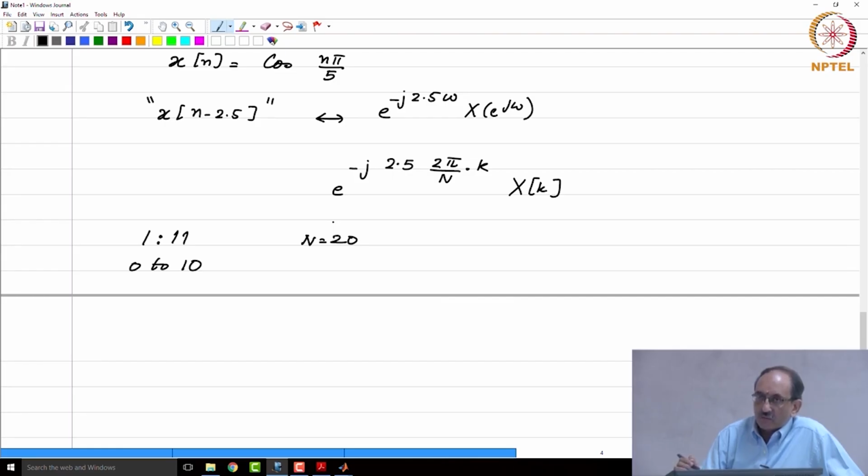And then when we form the inverse transform, we formed this vector x1, and then what we did was we took x1 as it is. To compute the time domain signal, you needed to compute the inverse DFT. For inverse DFT, you needed to form the 20 point DFT and then compute the inverse DFT using the IFFT command. To complete the whole transform, you needed to supply the missing half, which is the bottom part, corresponds to sampling of this unit circle in the bottom part.